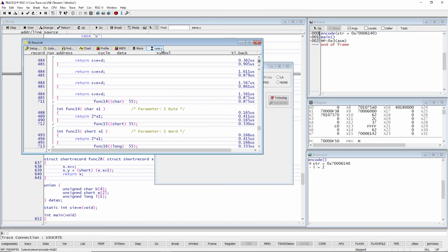In our example, we're using timestamps that are generated by the Tessent trace encoder. These timestamps are the only way to get time information for USB trace. If the trace is recorded with a Trace32 trace hardware, the timestamps are generated by the Trace32 trace module.